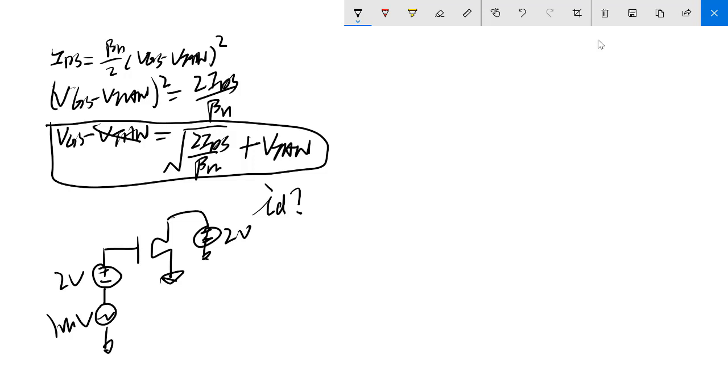The reason we want to calculate gm is because it's connecting the VGS to ID. If we are only looking at AC, ID actually equals gm times vgs. Keep in mind, vgs is the AC VGS, which is 1 millivolt over here. And gm, you can calculate using the VGS to get the saturation IDS flowing through the channel. After that, you should be able to get id.